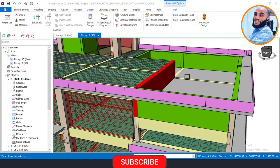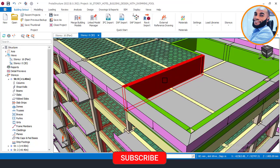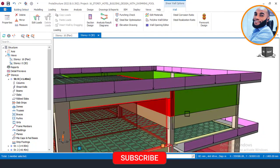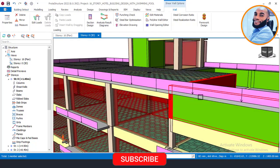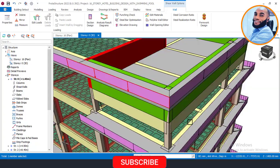Now to add your wall load on your retaining wall for this pool, I'll click on this place. Since there is no soil at the back of any of the pool walls here, because this is a rooftop swimming pool, we are not having any other counter force at the back of the wall.